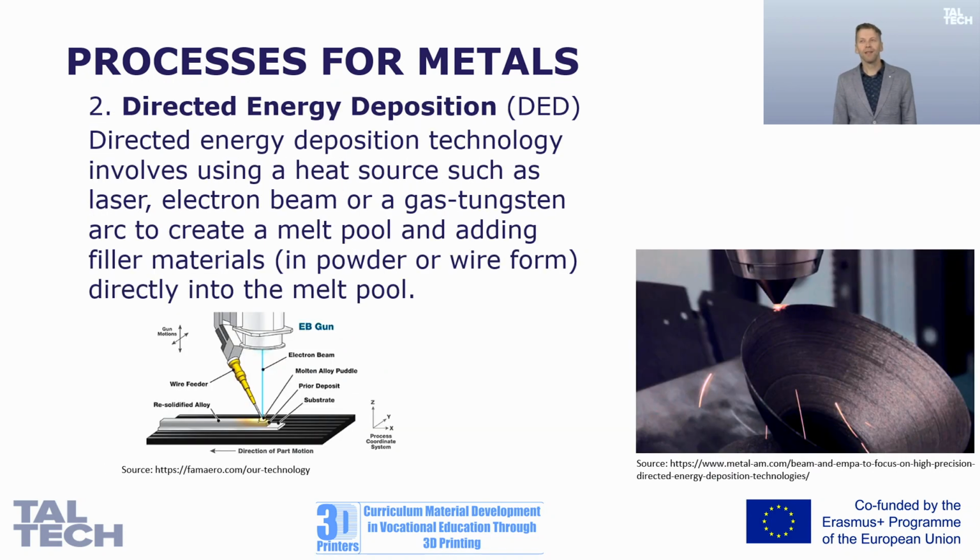The second approach is to use the directed energy deposition method. In this technology, we're using a heat source. It can be a laser, electron beam, or gas tungsten arc, and we're creating a melt pool, and then we add material to the melt pool, and that's how we are building the surfaces or the layers.